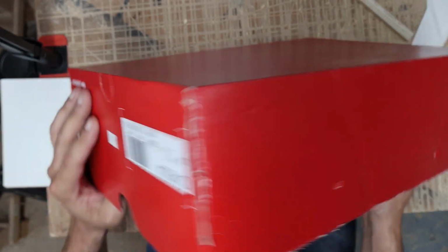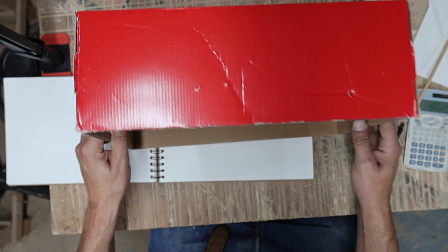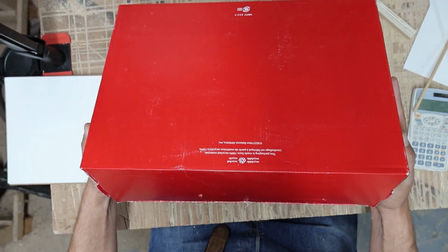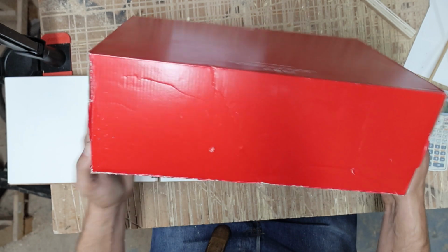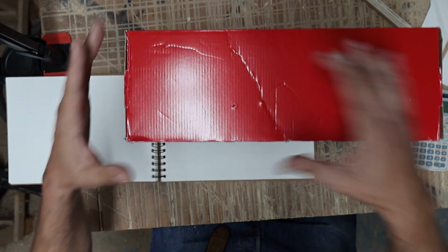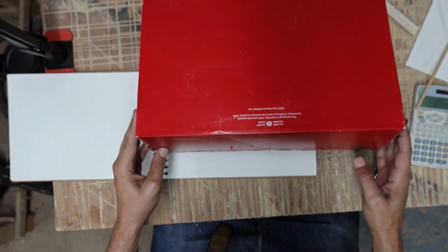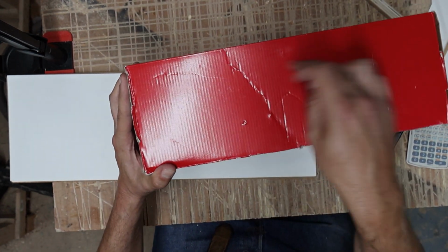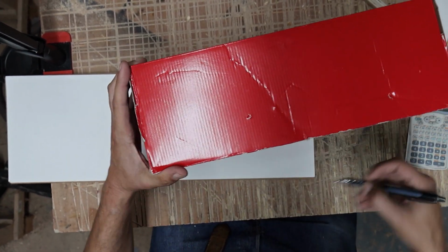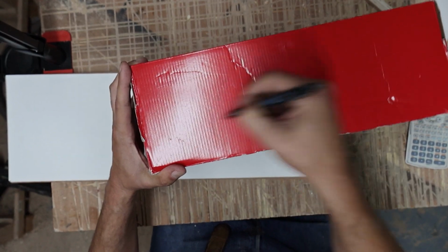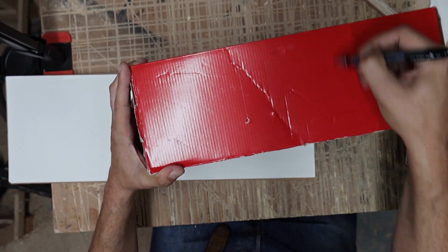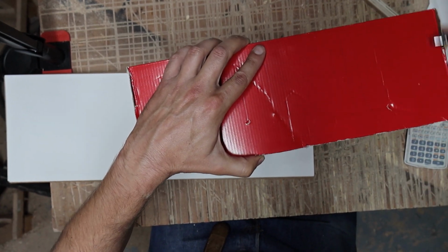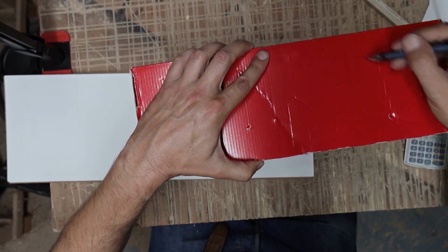So the principle of structural design is that every time we remove something from this box, we need to replace it with something else that replaces the same structural effect that this box has just on its own. So if we start cutting out panels, for example, let's just say we're going to have some windows in the side, then we'll probably stiffen up this with some beams and some cross bracing.